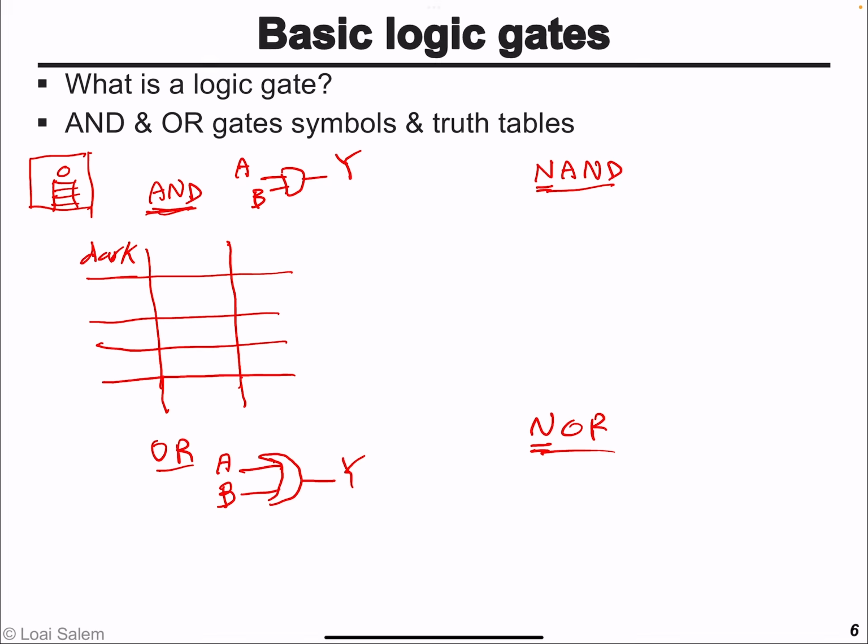If it's nighttime but there is no motion, no one there, so also there is no need to turn on the light, so the AND gate is going to produce 0. If it's dark and there is motion, this is the only time that the light bulb is going to be turned on. And as I mentioned, a simple way to implement this function is to just put two switches in series.